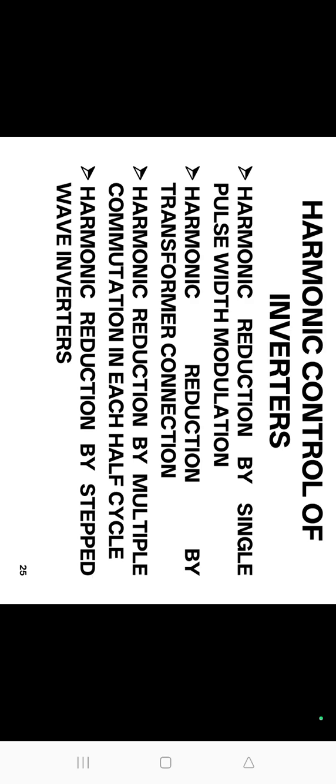These inverters are connected to a common load through transformers having turns ratio 1:3 and 1:1 respectively. Inverter 1 is so operated that its output voltage is VL1. The output voltage level is either 0 or positive during the first half cycle. During the second half cycle, the output voltage would be either 0 or negative.